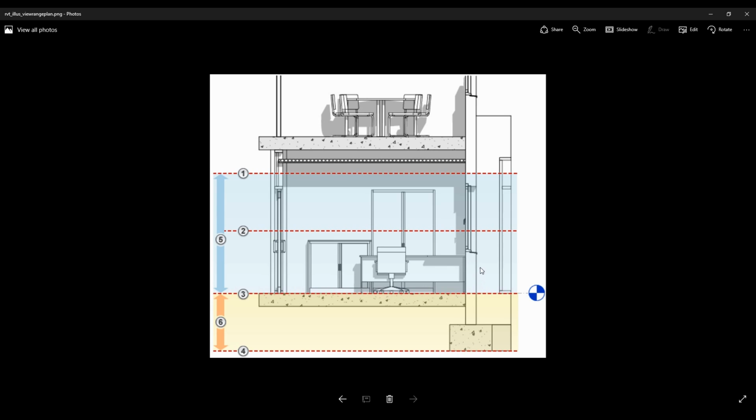So if you have any hatching in these walls, anything below that, like this wall, won't show up because there's a window above it. So what I mean, in your 2D walls in plan view, it'll show this window. It won't show like a solid wall. And that's typically what you want.